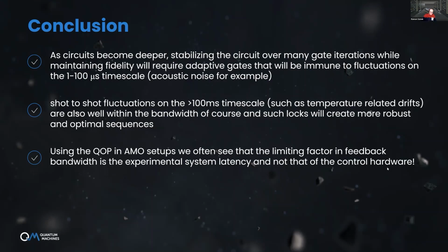And then there are the limits of this bandwidth. So you would also want to do maybe intra-gate calibration, and you can do that, by the way, with the simulator pulses. So pulses which are tens of microseconds or 10 microseconds long, where you cause some arbitrary frequency chirp, frequency modulation, and amplitude modulation.